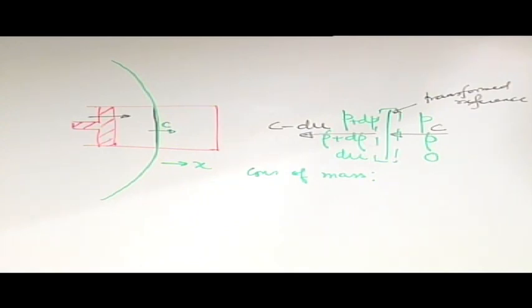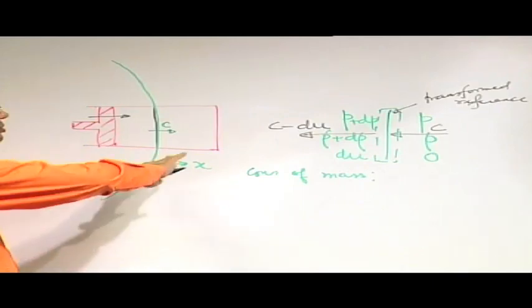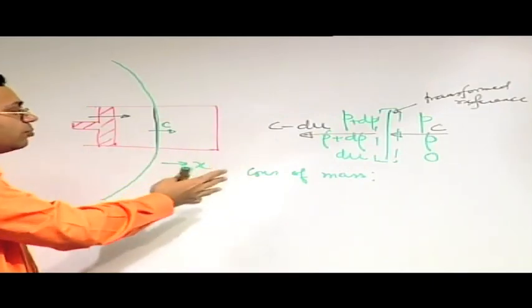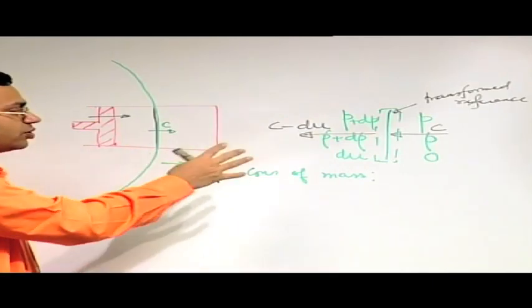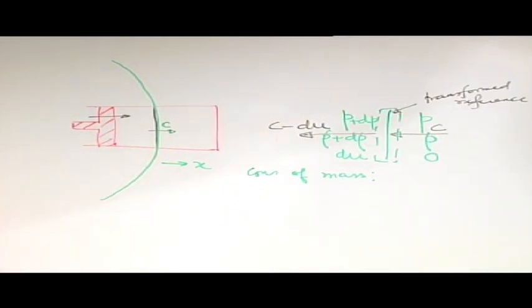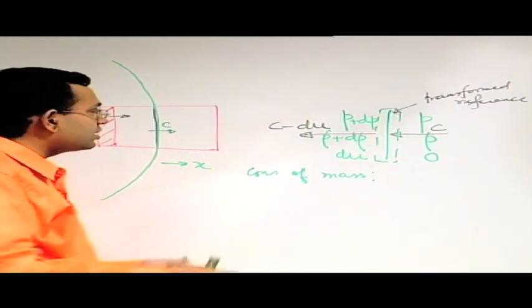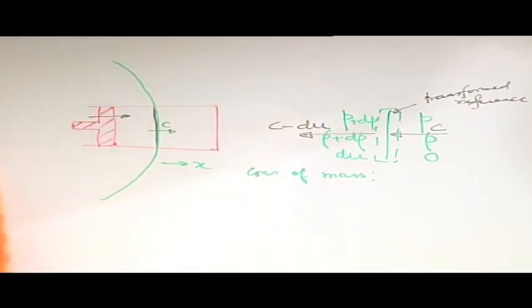One of the important assumptions that we are going to make here, and possibly for most of the important fundamental theoretical derivations for compressible flows, at least within the scope of this particular course, is that the flow is like a one dimensional flow. That means u is not varying with y.